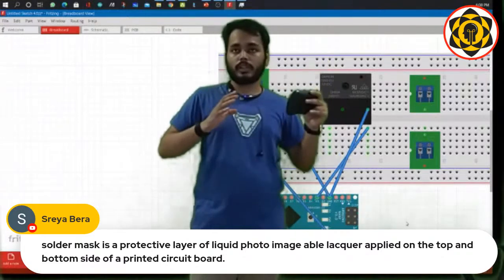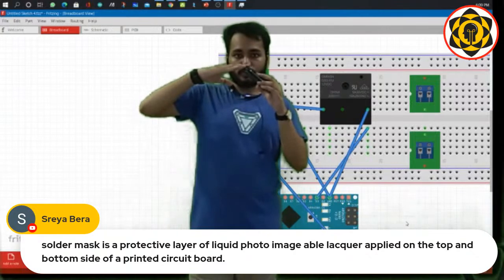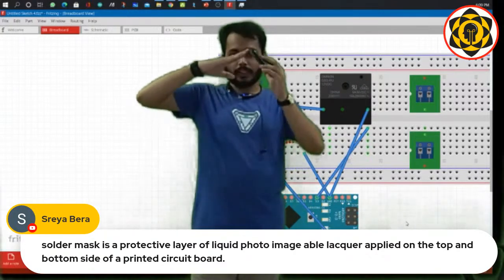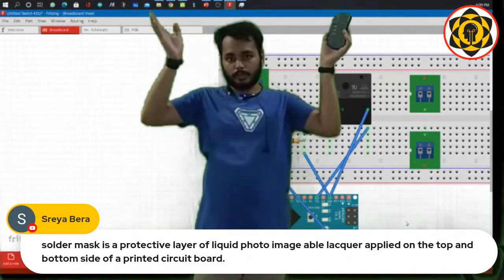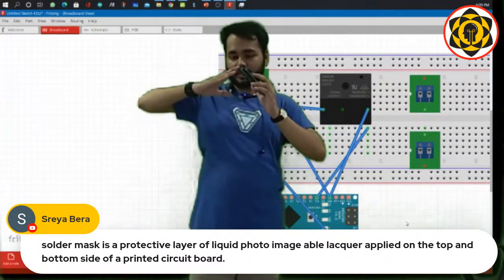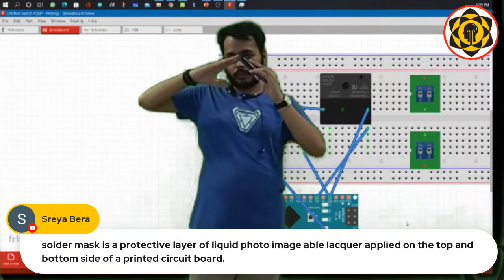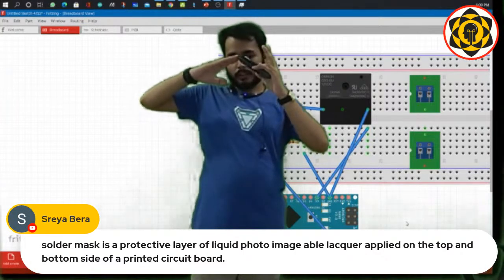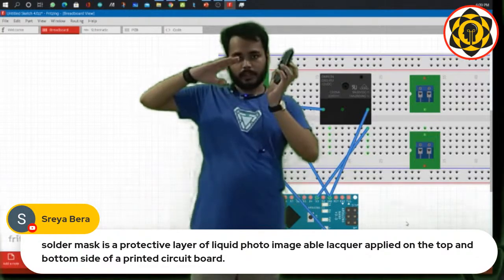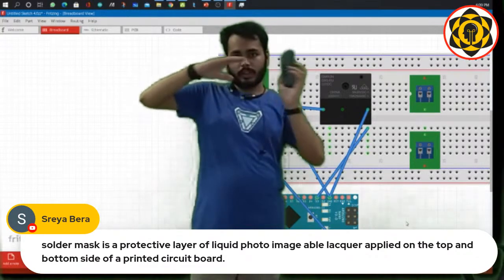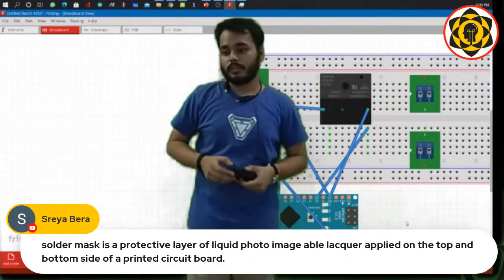The microcontroller gives a positive signal, it energizes the coil. Now the coil moves the switch to connect the terminal, and this circuit gets connected, and then we flow alternating current through this circuit to light the bulb. Once again, when the job is done, when it's time to turn off, the microcontroller goes low, turns the supply to the coil off, so the coil gets disconnected, and due to the spring, it goes back. So the connection is open now, and the circuit is not closed, so the alternating current gets disrupted, and the bulb turns off. So that's the idea, I guess.